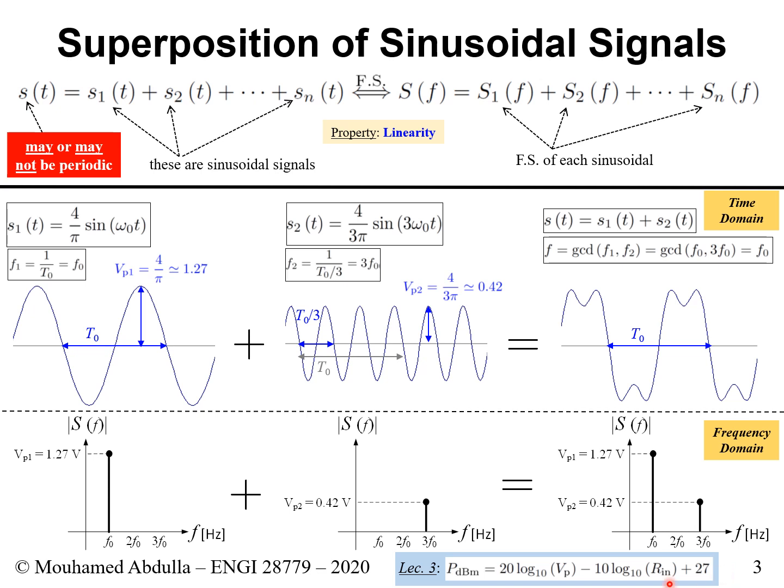You put your V peak here, and you put the internal resistance of the RF input of the spectrum analyzer here. If it's not given to you, you could always assume 50 ohms. This is a reasonable number, and this allows you to find the values of your spikes in the frequency domain in terms of dBm. So if we do this, let's see what we get.